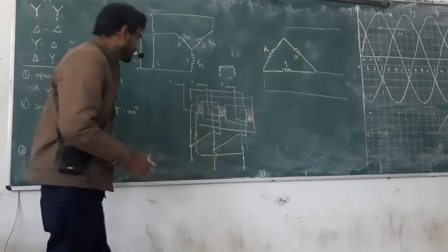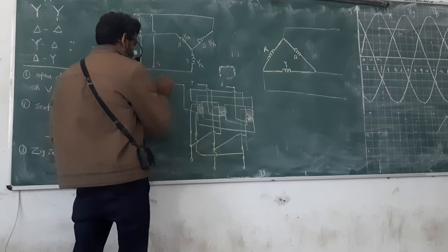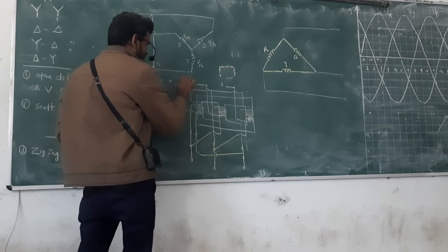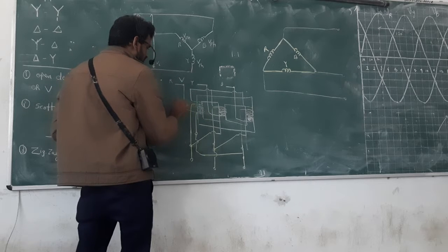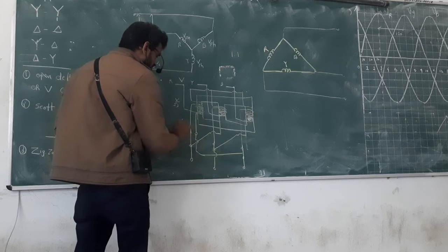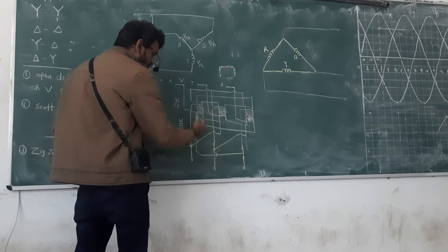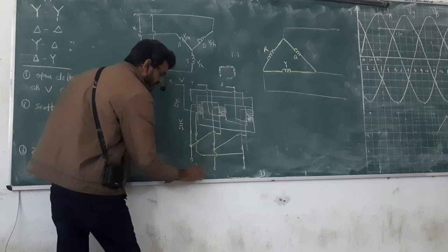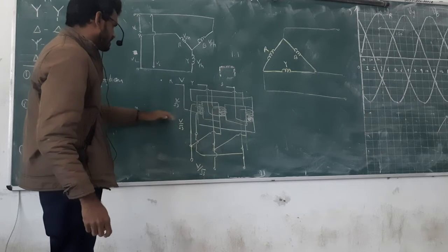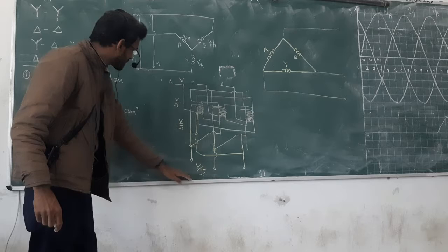So here we see. Let's say I have V voltage. Then here V voltage is there, then the white winding has V divided by root 3 voltage. Yellow will induce V divided by root 3. And it is connected in delta, so it will give the same voltage, V divided by root 3. Okay, so line voltage, phase voltage, primary side, phase voltage, line voltage, secondary side.